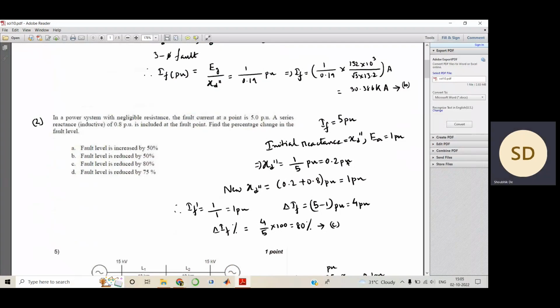It states that in a power system with negligible resistance, the fault current at a point is 5 per unit. A series reactance which is inductive in nature of 0.8 per unit is included at the fault point. Find the percentage change in the fault level. Means the fault current change we have to find. So the initial fault current was 5 per unit, right? And the initial reactance...